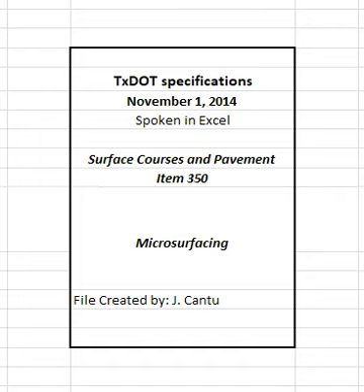4.6 Tack coat. Apply tack coat uniformly at the rate directed by the engineer when shown on the plans. The engineer will set the rate between 0.04 and 0.10 gal of residual asphalt per square yard of surface area. Apply the tack coat in a uniform manner to avoid streaks and other irregular patterns. 4.7 Material transfer. Minimize construction joints by providing continuous loading of material during placement. Remove oversized material before transferring the aggregates to the mixing machine.